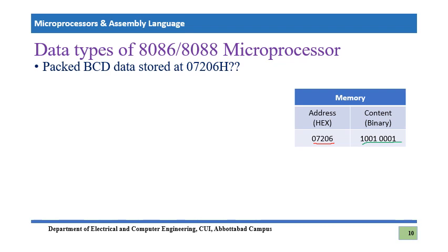Let's see. If you remember, it is a packed BCD number. That means these least significant 4 bits are one BCD, that is just one BCD 1, and this is also a BCD because the 4 most significant bits are also a BCD.